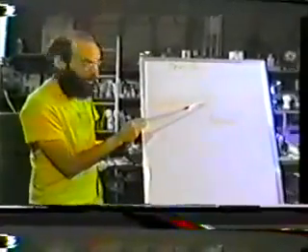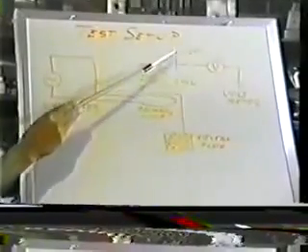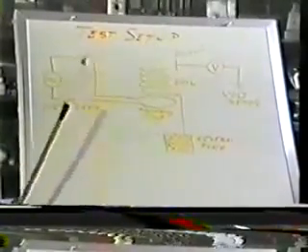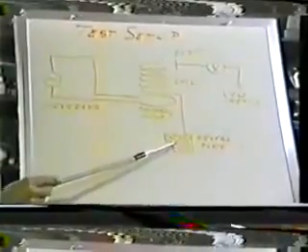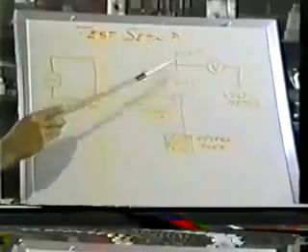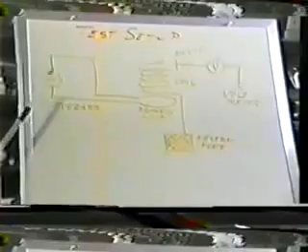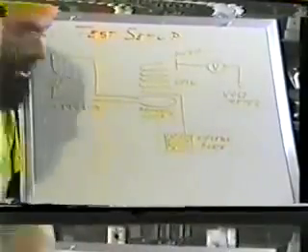This time our transformer couples the generator energy to the first turn of the coil, which is wound of fairly fine wire. And then we have a capacitive probe pickup to measure the voltage rise at the end of this coil. And at the neutral end of the coil, we have a large capacitance plate to produce our impedance dissimilarity, so we end up with a quarter wavelength rather than a half wavelength resonance on this coil. Now we'll look at our test setup again here.